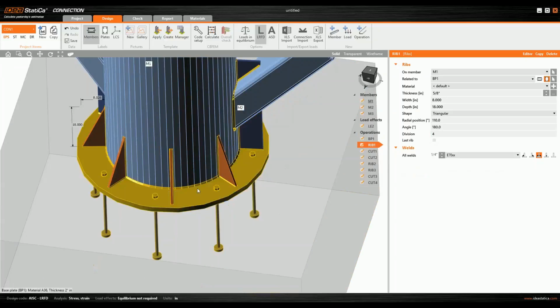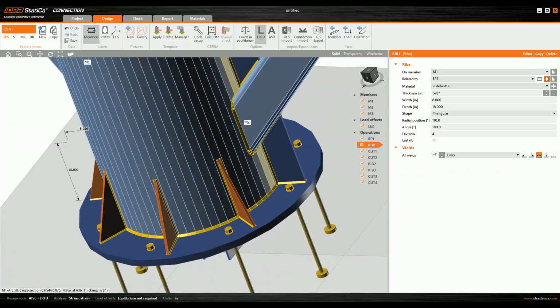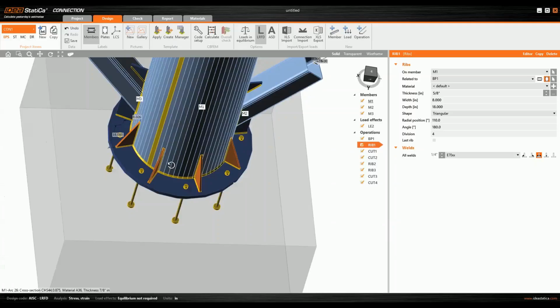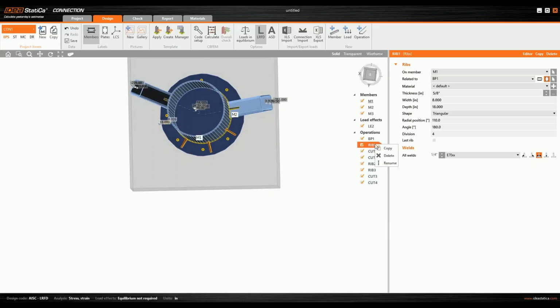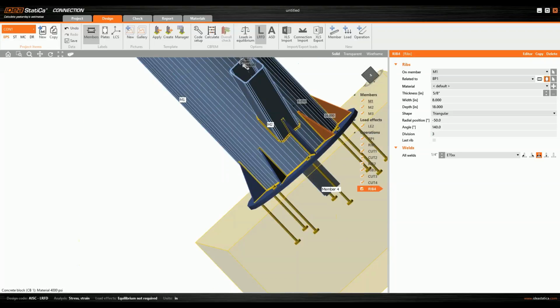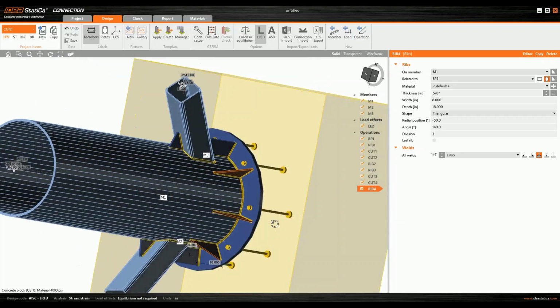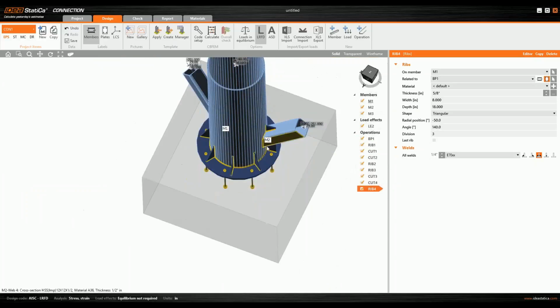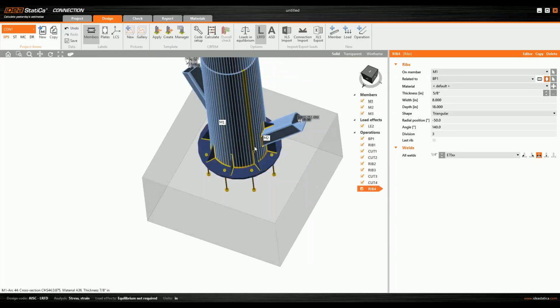So now we get the stiffeners just here and not under the members, while they have their own bigger stiffeners already in place. So now I just copy this operation and change here the parameter, 140 for the angle and 3 for the number, and we got it on the other side as well, right in place. So just a small trick how to edit the stiffeners along a member.